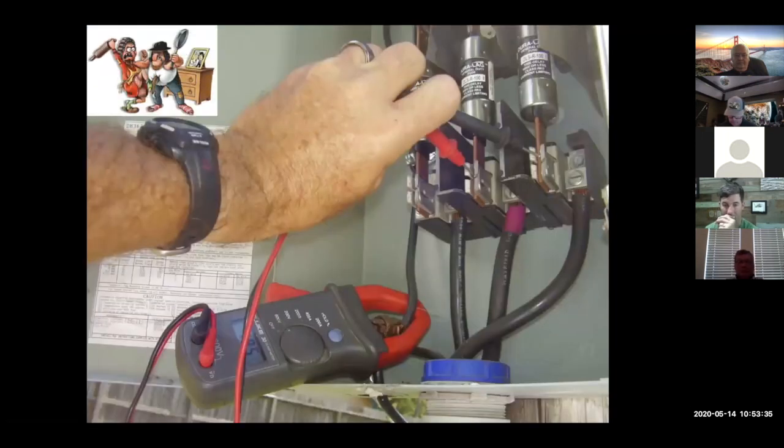Okay, here's a friend of mine. Look at here. He was checking this. He was talking on the phone, and he's checking voltage here inside this panel. And he's got his voltmeter there. He's got a ring on. His hands are naked. This panel is hot. You can see on the meter it's got voltage there. And my little deal up in the top left, these people are beating each other on the head because this is wrong. It shouldn't be this way. We need to be protected.